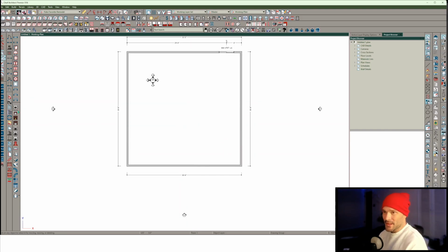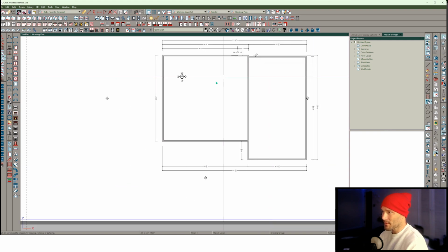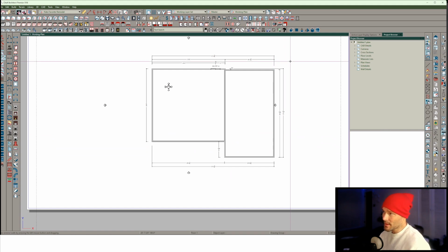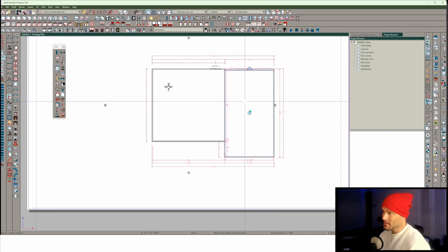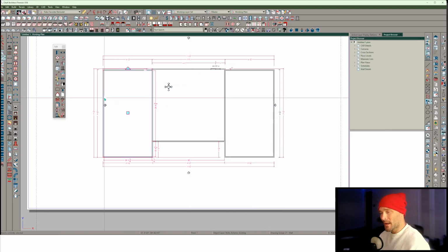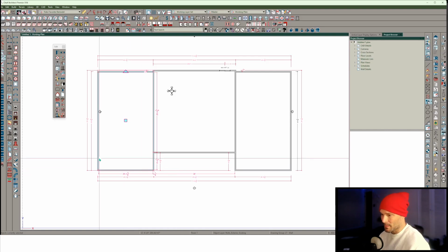But here we go. We'll just start with the building. We've got a projection that goes all the way across, and then all of a sudden this extends out, and we've got two gable ends, okay? And I'm not even going to worry about dimensions in this case, and I'm not even going to worry about alignments. With the wall tool active, if you are in a contain selection mode, I could just contain select all those things and copy reflect about the other side. And now I have that second gable established, okay?